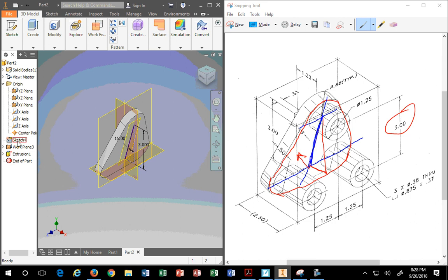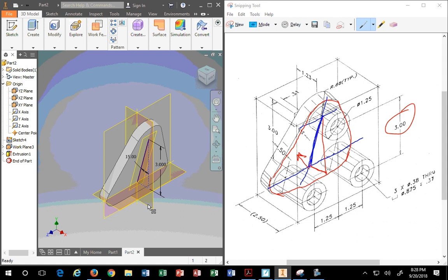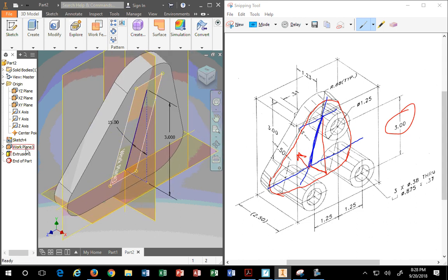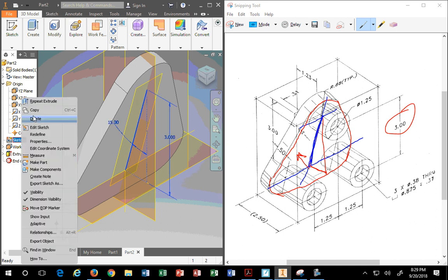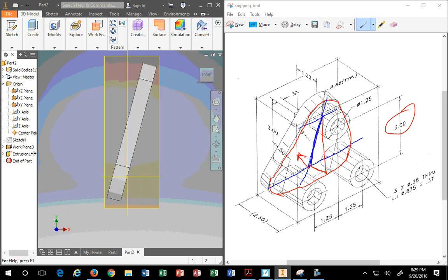Once this is done, you see, I left this in so you can visibly see that. That's how it needs to look, guys. If you extrude the wrong way, you're going to lose your position for where these have to be. So you have to do it this way. So you extrude back. Then I'll just hide this. I don't need to see it anymore. When you look at the front view, see that? Your plane is on the front face, and you extrude it back.